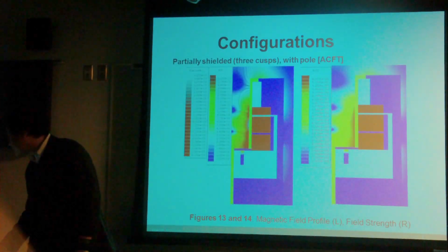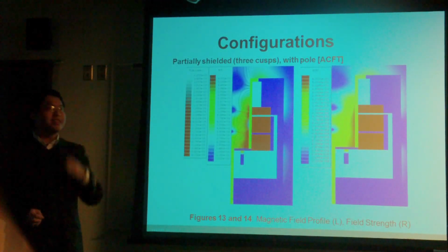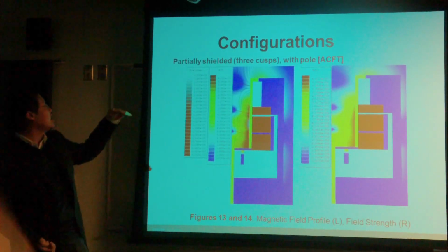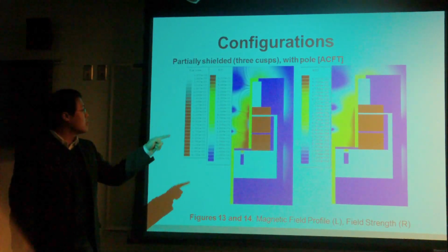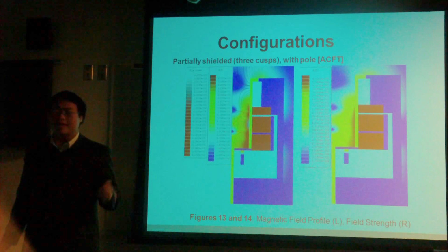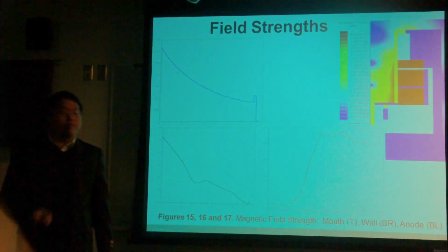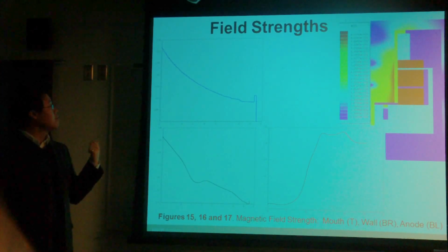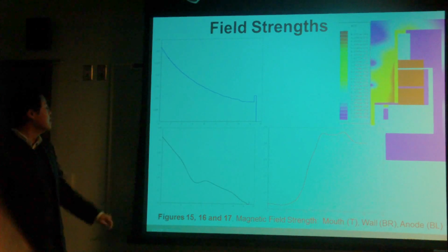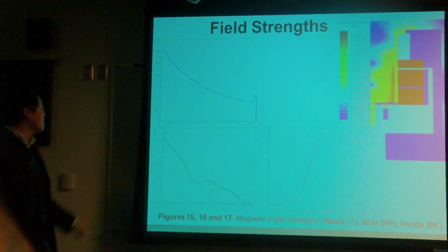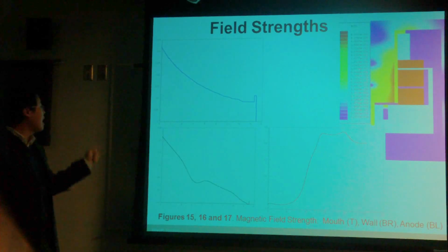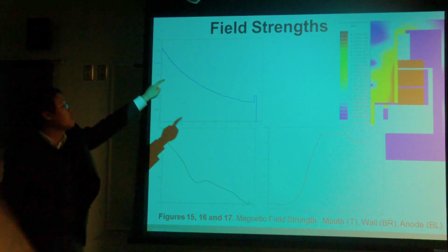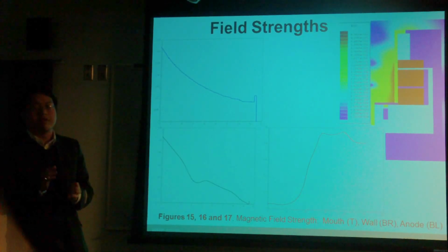And we eventually came to a design that had most of the aspects that we really desired, which included that somewhat flat separatrix at the exit, and somewhat stronger field strength. Here you probably see a better gradient with better projection, but here are some plots that tell you a pretty good idea of the topography on this example. So you have this design where you have these three plots. They're magnetic field strengths in units of Teslas. On the top left plot, you have magnetic field strength across the mouth of the thruster, where essentially that would be where the separatrix would be.